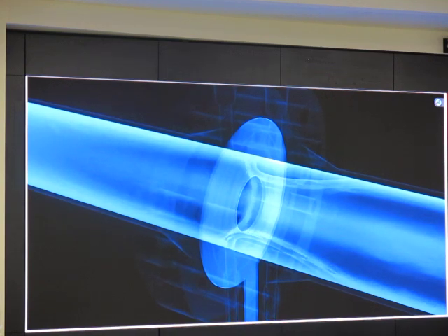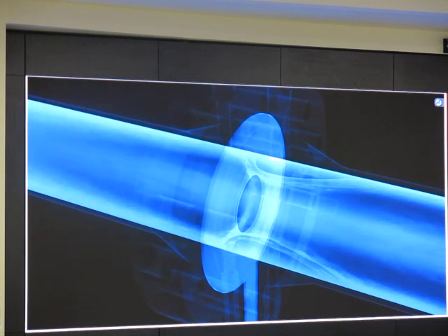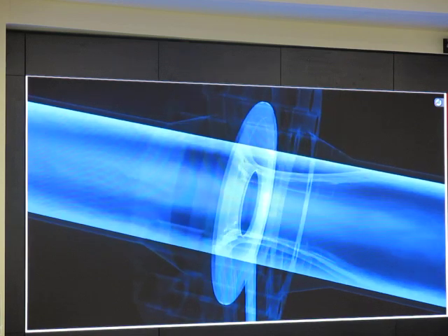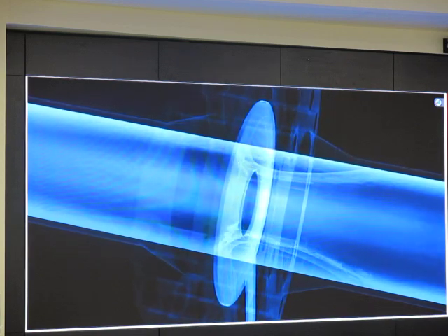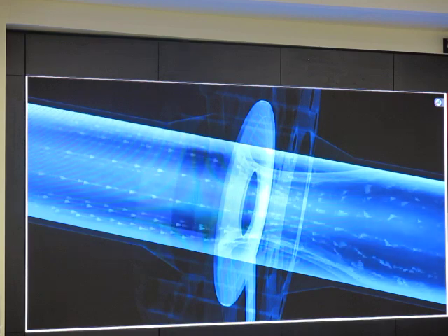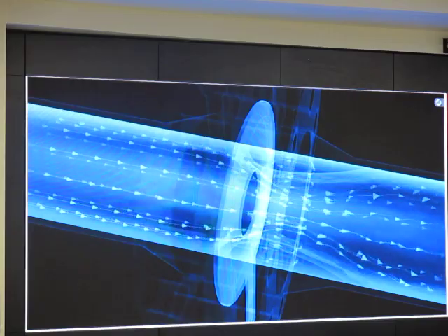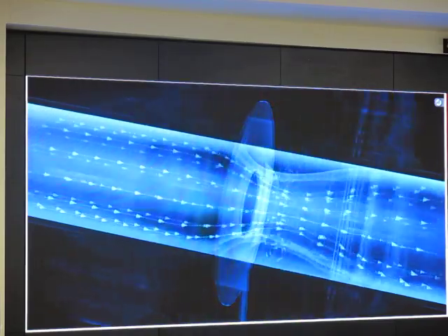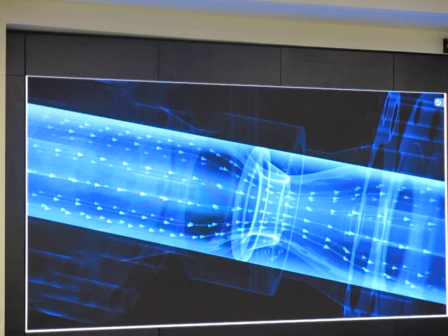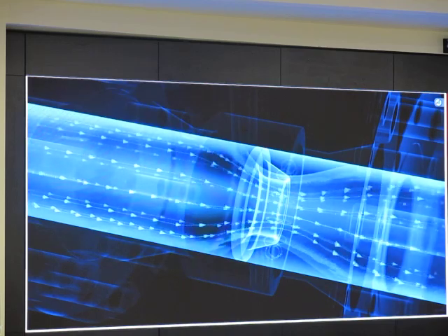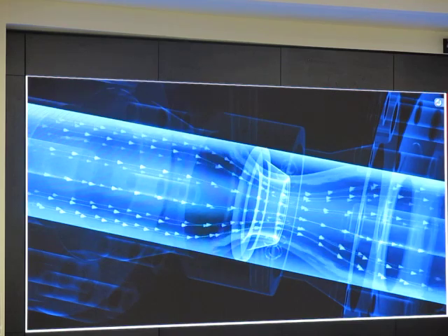However, other designs are available for certain measuring tasks to minimize undesired effects, such as excessive pressure loss or abrasion of components due to solids carried in the fluid. This demonstration shows that an abrupt restriction generates severe turbulence in a fluid. Nozzles with a rounded, funnel-like inlet clearly reduce turbulence and thus create less pressure loss. Nozzles are particularly suitable to higher flow velocities or to fluids with abrasive solid particles.